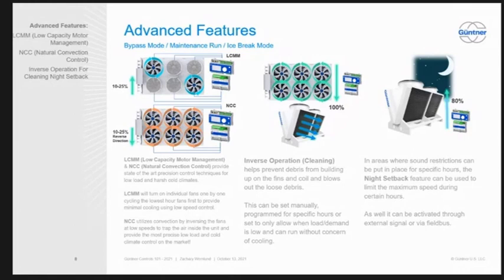Especially with your stuff, having that set up, because the way that they're all controlling them off drop leg temp for CO2 has been nonstop problems. And until we convince them all to not use drop leg temp any longer and use pressure, at least dropping down to one fan in the wintertime would save a lot of that expansion and contraction, I would think. Yeah, this is a standard feature on our end.